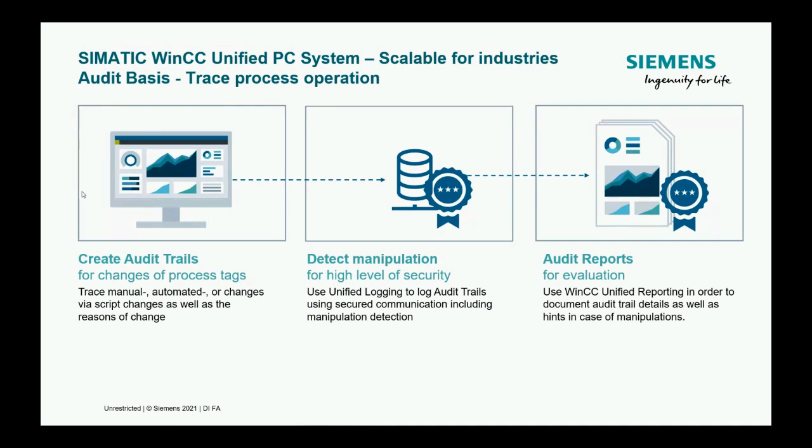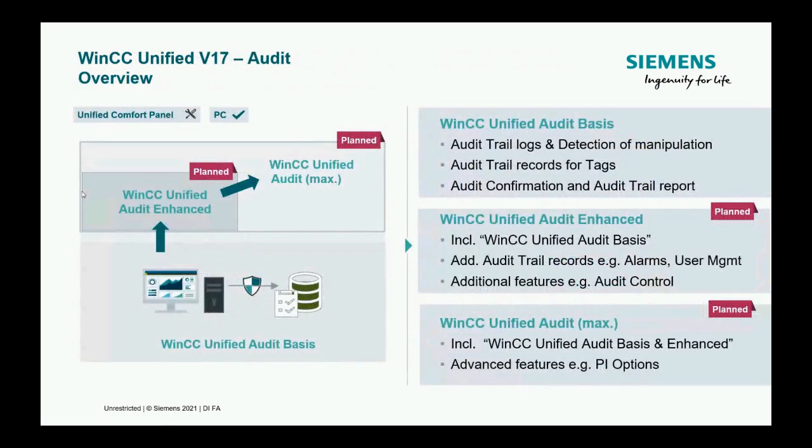So I've mentioned we're talking here about audit basis. If we're calling it basis, it means there must be something beyond basis, and that's exactly right. So the plan is to release 2 further versions, which are the WinCC Unified Audit Enhanced and the WinCC Unified Audit Max. The basis, as we just saw, covers logs, manipulation, and process tags, and includes the ability to report on these. The WinCC Unified Audit Enhanced includes all of that functionality, but in addition, we can produce audit trails based on alarms and based on user management.